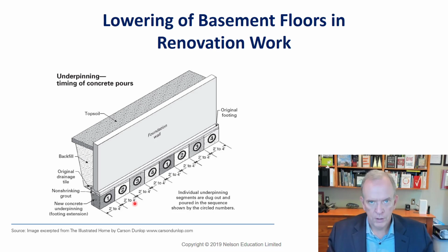You get an engineer to do an engineered set of drawings for the underpinning, and you follow their diagrams very carefully. This is very serious work. If you mess it up, the house can collapse very quickly. So you want to make sure that you do it well so that it's able to support the loads above it. Every year you'll read in the newspaper, oh, this house collapsed, they were working on it due to underpinning. And when that happens, it's not a good situation. So you want to follow it very carefully. You would excavate under all the ones.